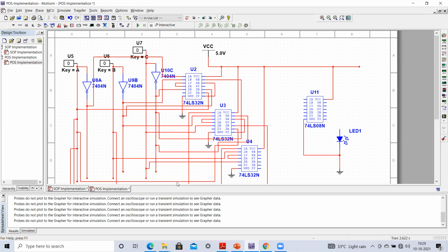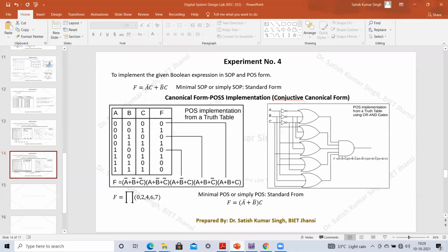Now you have to make the connection with the AND gate. All this output has to be connected to the AND gate. So you can see this is our first output of our OR gate, first output that has to be connected with the AND gate. So here it is AND gate, our 74LS08. So another input should be this output, because it is just a 2-input AND gate. This we have implemented this function. You see this, this 2 has to be connected. This we have already connected with the AND gate, and then we are going to get the output.